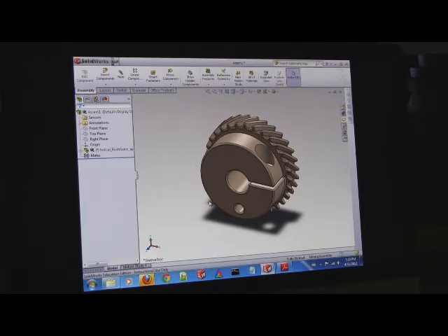Okay. So this gear, click it and try to drag it around. It will tell you the selected component is fixed, it cannot be moved. The first part you put in an assembly is always fixed. It does not always fix it intelligently. One would hope that it aligns all of the planes properly. It does not. And remember how I said that you never, ever, ever in a billion years want to fix anything in SolidWorks? The first thing we're going to do is undo that.